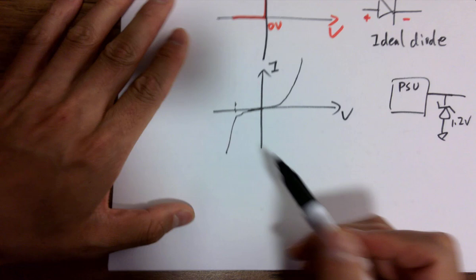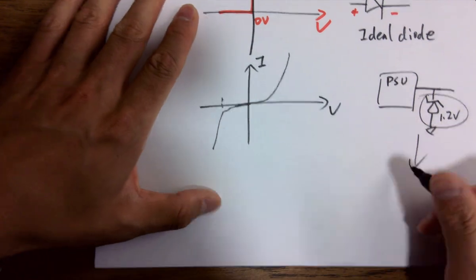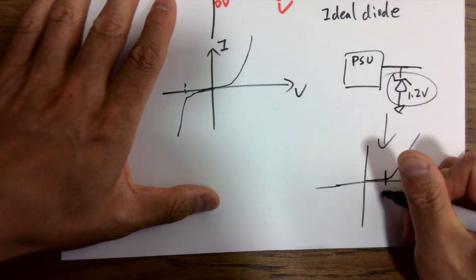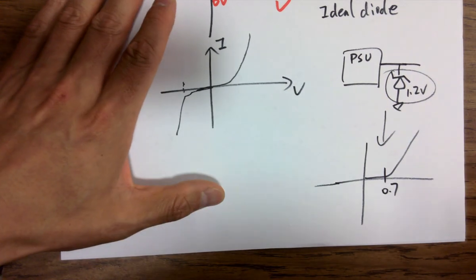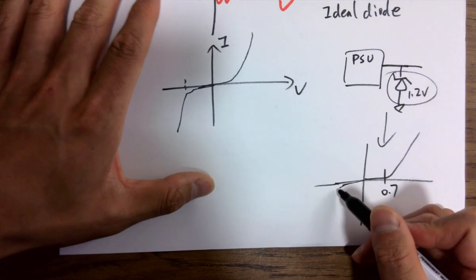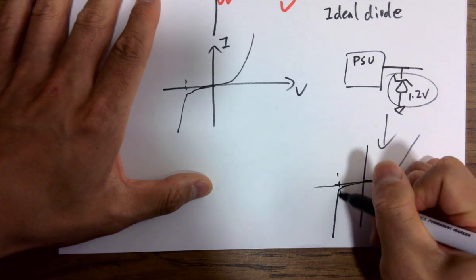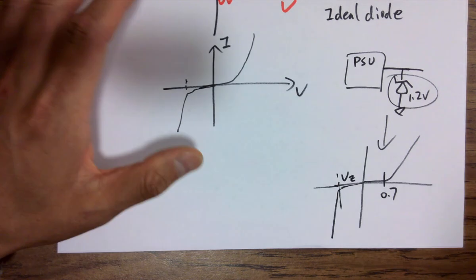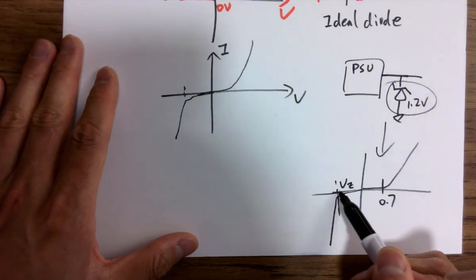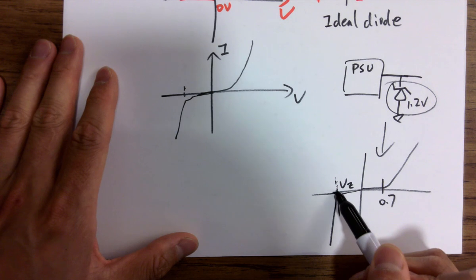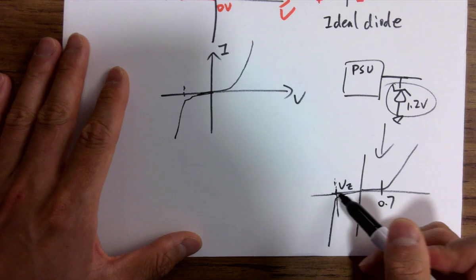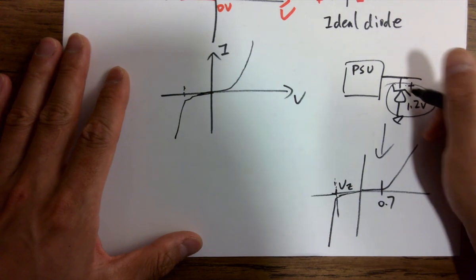So what does that mean? If you look at the Zener diode's curve, first, a Zener diode is a diode, no doubt. After the 0.7 volts threshold voltage, it will start conducting current through it, right? But whenever it's going reversely, at a certain point, it breaks down. This is called VZ. Because you are reverse biasing this, VZ shows up at a negative X coordinate, so it's actually plus minus VZ.